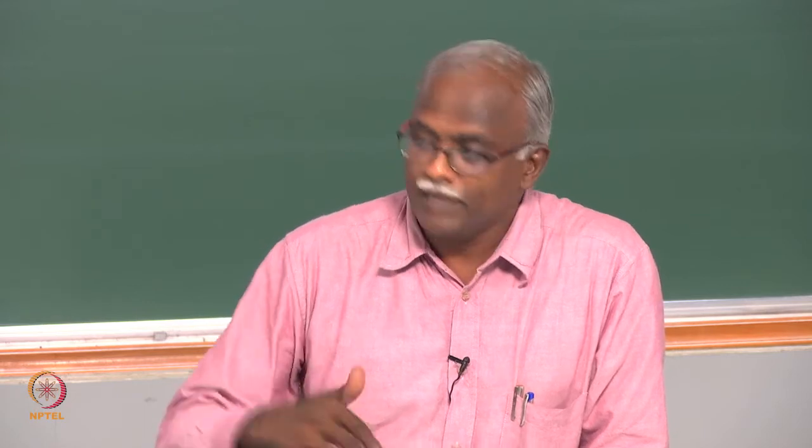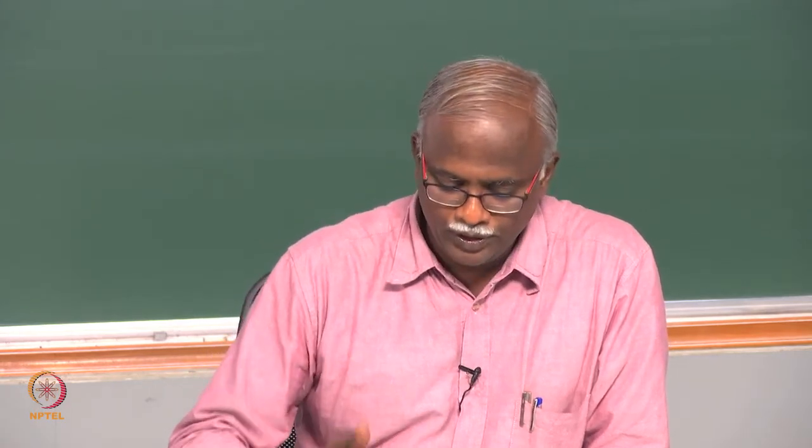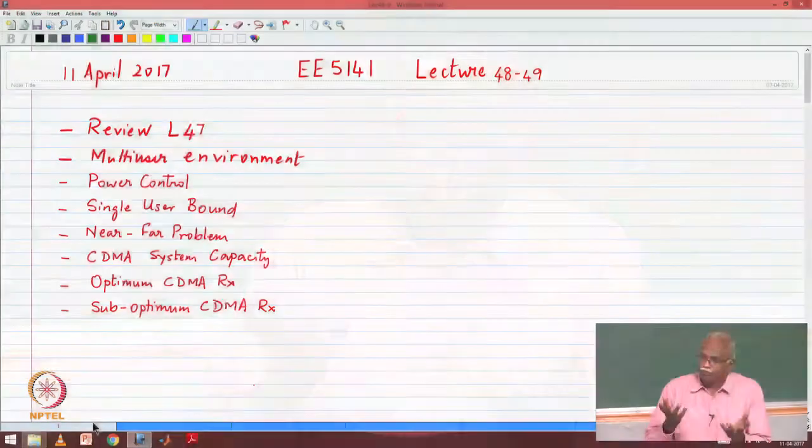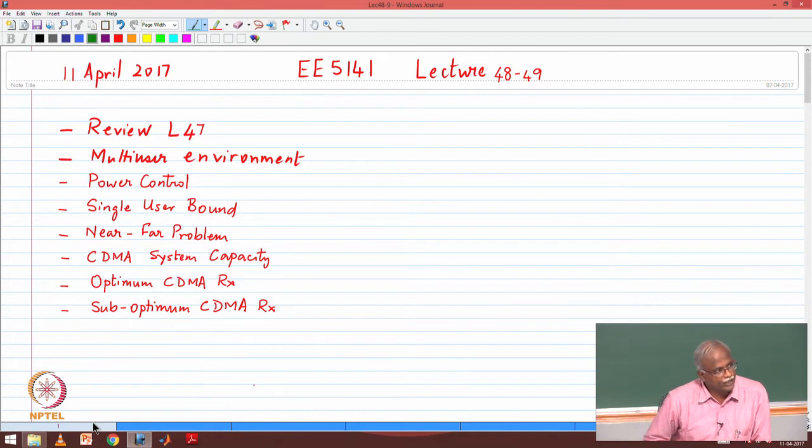What we will cover today would be probably the heart of a CDMA system. We have talked about multipath environment, so now we are going to go into the multi-user environment. Once having understood the multi-user environment, we will talk about the impact. Why is power control so necessary for a CDMA system? If you remember, when we talked about channel inversion, we said that there is a phenomenon called the near-far problem. So today we will discuss the near-far problem and what effect it has on CDMA system capacity.